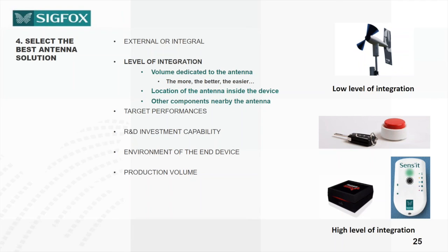So the size of the device will be important, but also again the volume you dedicate to the antenna. Basically, the more volume, the better, the easier. Again, about this level of integration, you really need to select the best location for the antenna inside your device. And again, the other components nearby the antenna.